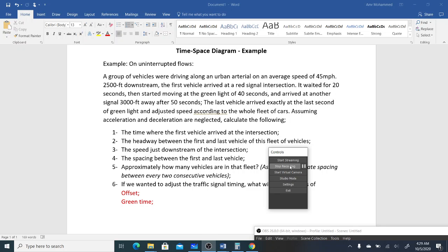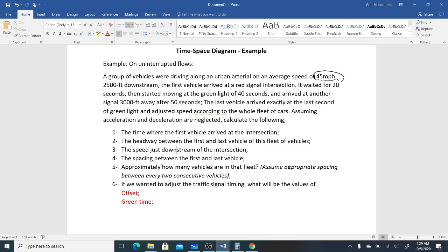In this case, guys, we will need to change our units, definitely not in miles. We need to put it in something where we can put it on a curve. So we're going to change our miles per hour into feet per second. And to do this conversion, the 1.47 secret number that we use in all our transportation equations will be the one conversion factor that we use. I'm going to show you in a minute how you do that.